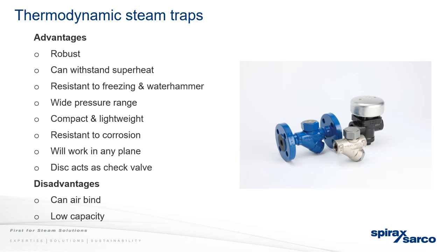Like for main lines, for example, if that's the question, then we would generally recommend thermodynamic steam traps. They are robust. They can handle a lot of the water hammer. They are quite tough, and they're quite small as well, provided they're installed properly in a proper drop pocket. Yeah, exactly.